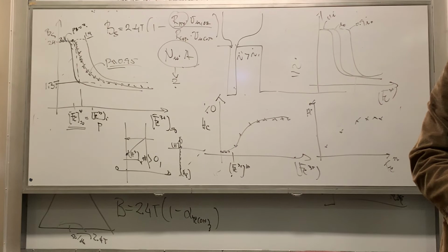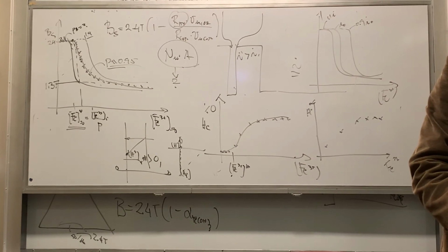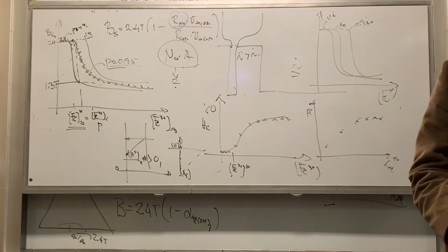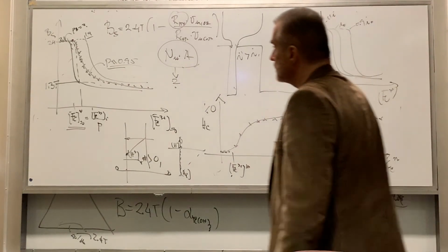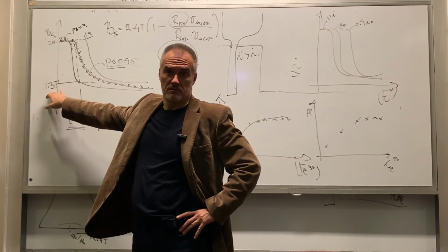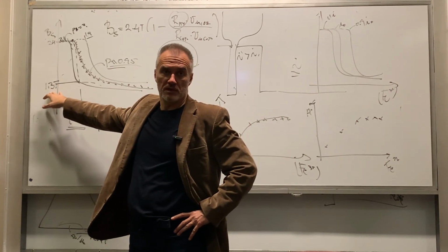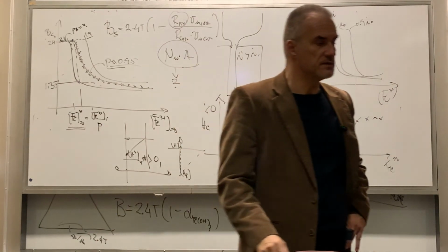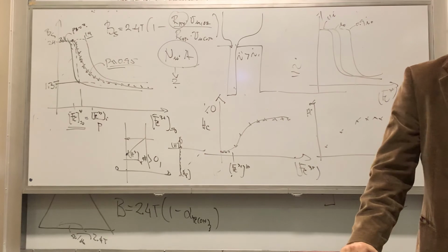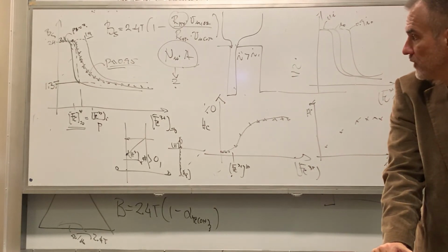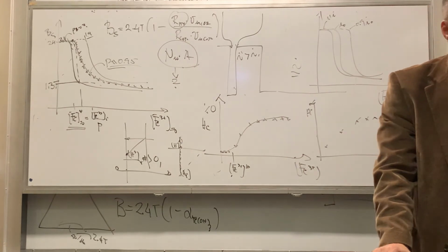And again, it depends what kind of alloy you want. Sometimes you want them to be resistive, and the moment is not the most important thing. Well, you can probably live with this type of moment, but they will be super resistive because they're going to have a lot of oxide incorporated, which is an electron scattering phase for the current flow. Any questions?